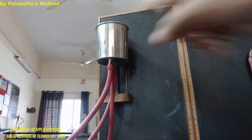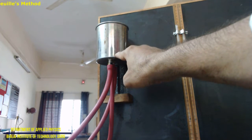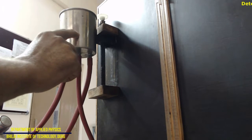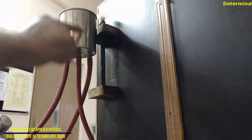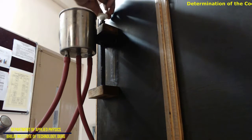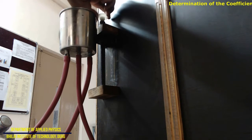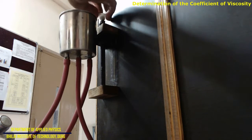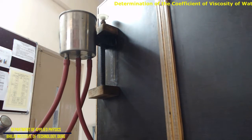Then there is a constant level tank. This is known as the constant level tank. I will explain how it is a constant level tank. This constant level tank is attached to a screw. This is the screw with the help of which we can lower this tank or raise the level of the tank. To lower or raise it, this is the head which is rotated. You can see when I am rotating it, the container is coming down. So in this way we can lower or raise the level of the tank.